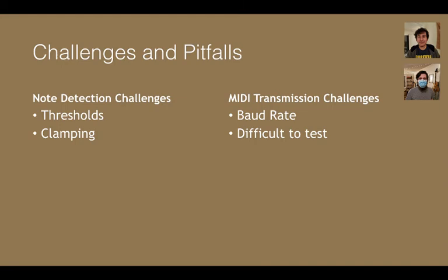We also found a few problems originally with the MIDI transmission, where the baud rate wasn't being generated cleanly, and that would cause the output to not be aligned to the actual baud rate required. And to fix that, we ended up using a different clock source whose frequency was a multiple of the baud rate.